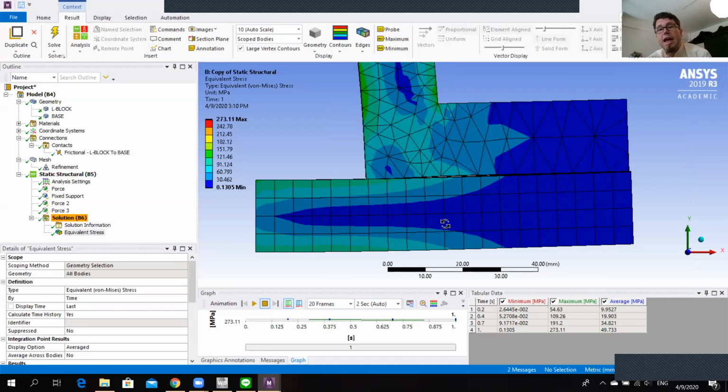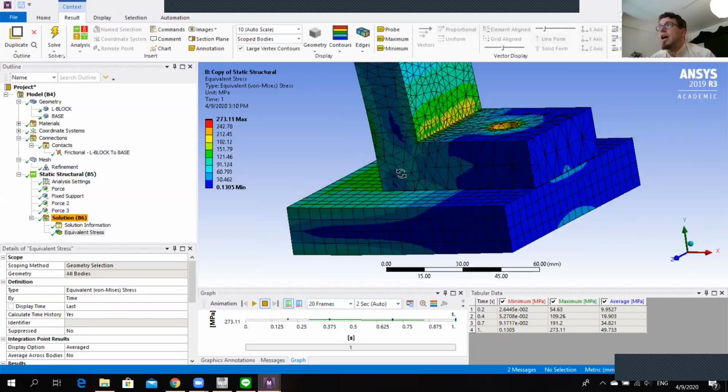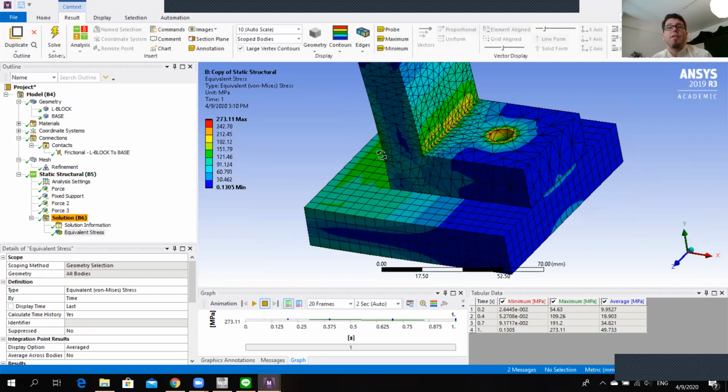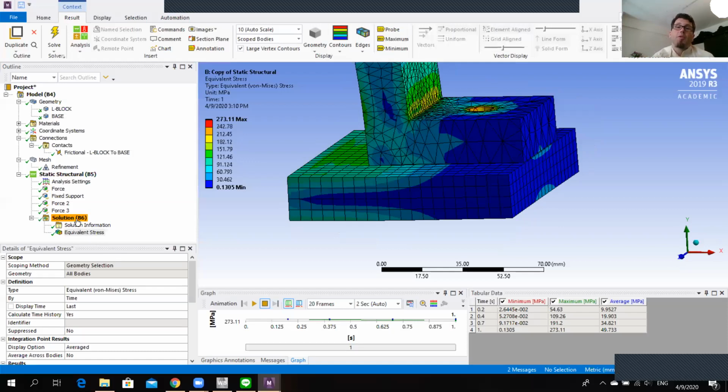We have constant forces acting on the upper and lower part. Now, if you stretch the screw, of course, it will react with a higher reaction force. And this is modeled wrong here, basically, because our screw force is modeled as a constant force. In real life, any try to stretch that screw would result in a higher reaction force. So I believe the gap that we see in this simulation would be larger than in real life, because in real life, the screw force would increase. Here it's constant, so the resistance against the opening of this gap is a bit lower. But this doesn't really matter because we were never really interested in looking at the screw anyhow.